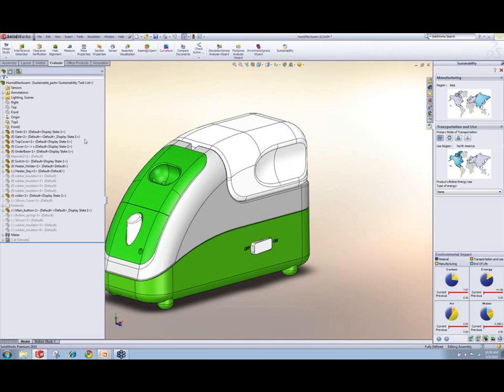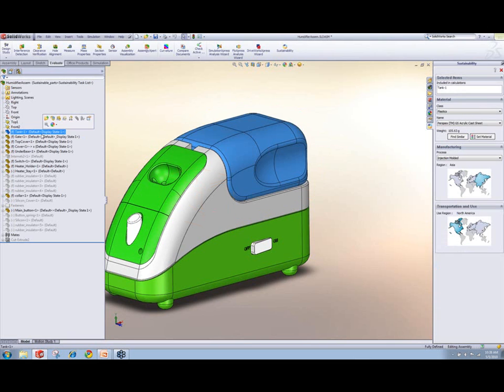Now if I click on each of these individual parts, you'll notice that it shows your actual model design name, and it shows you the actual material that's selected. These are all materials that have been pre-selected inside of the models. What I've done is select a group of them, or each individual one, and set the material from here. I've done a set material. This way I can ensure I'm using PE International's certified materials for my analysis.